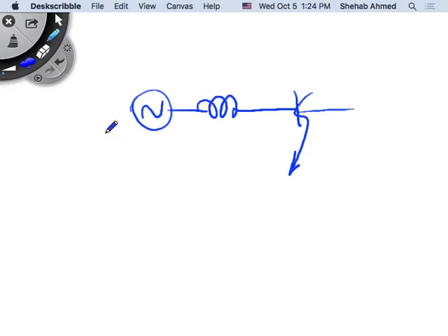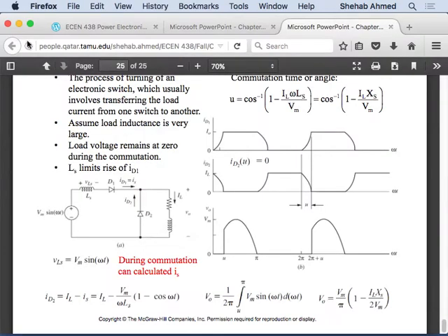So what is the effective model? Theoretically there's some small resistance, but typically we neglect that in power systems and we just consider the reactance here. That's why source inductance is important, because as a power engineer, you are going to connect your big drives in RasGas or Qatargas or wherever to the utility. The utility, how do you model that? You model that as a voltage source and an inductor in series. And that's how you would calculate the fault level at your utility.